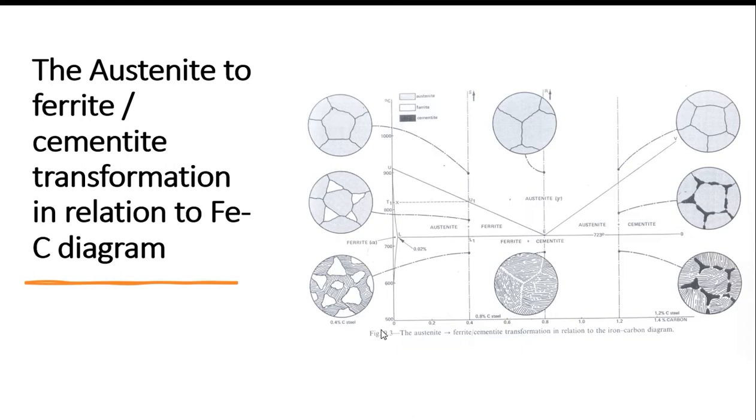If you go along the horizontal line, you can see the changes of carbon percentage. Here you can see 0.4 carbon and 0.8 carbon where the change occurs, right? For both you have to identify the same temperature also. Due to the change of carbon percentage you can see the structure change, right? Here you can see cementite also forms above the percentage of 1.2, right?